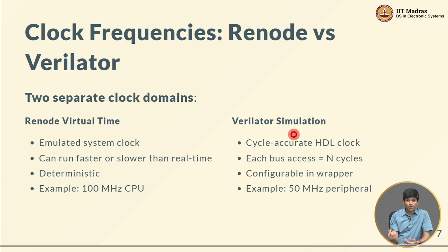Now the point over here is, this is also a simulation. As you might have already seen, you might say that your Verilog code is running at a 100 MHz clock, right? You generate a clock of 100 MHz, but the speed at which it gets evaluated internally may not be 100 MHz. It may effectively only be able to generate something like a 100 kHz toggle rate for the clock, right? It depends on how fast your processor is and how complex your Verilog design is, okay?